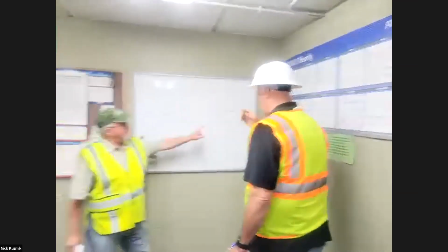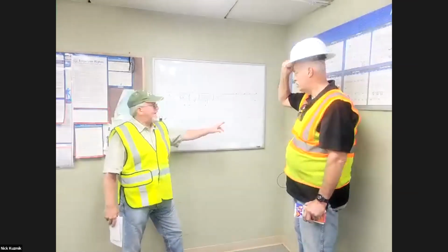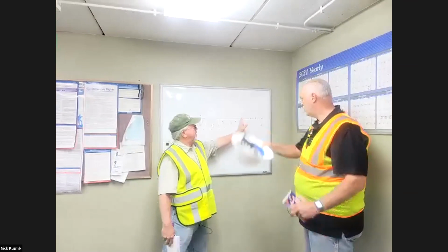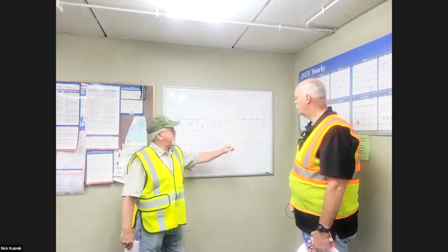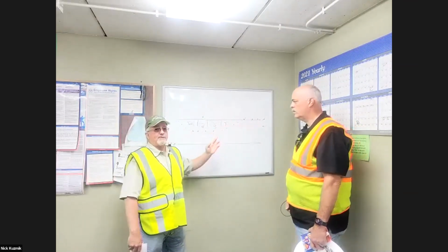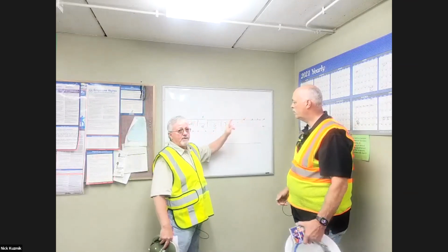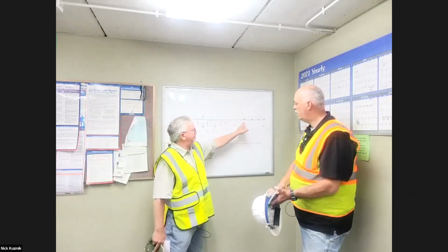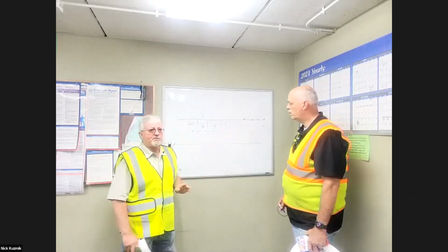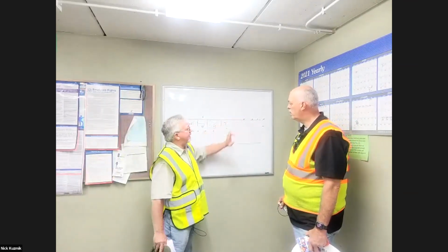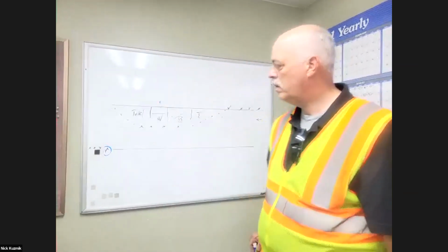The flagger should be stationed right at the beginning of the taper. Again, with adequate spacing between the signs. Again, you want to be off of the road on the shoulder, away from any potential missed driver without paying attention. So ideally, on the right side of the shoulder here, just before the taper. You don't want to be in the middle. You don't want to be outside. You can't trust the driver that's coming at you, whether they see you or not. So on the right side of the shoulder. And the other one would be, again, on the right side of the opposite side.